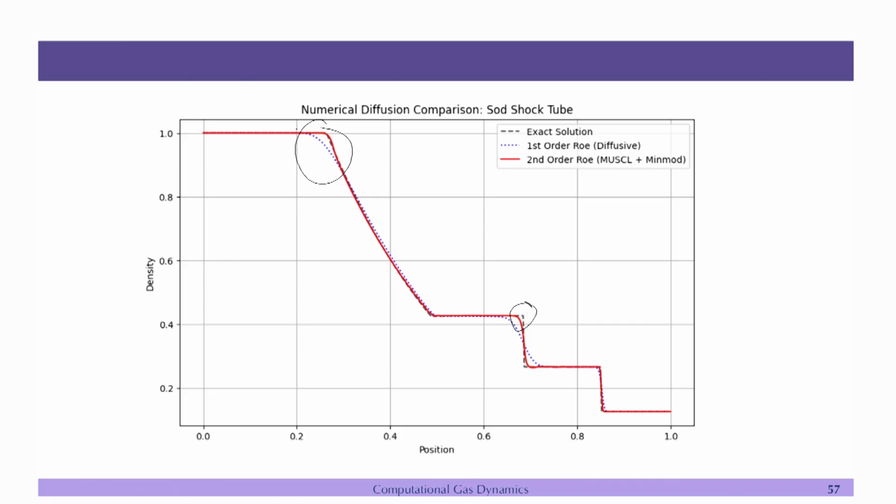And when we are talking about computational gas dynamics and flow which has shocks and expansions, it's a slightly different business, because you have strong discontinuities at different locations that you need to deal with. If the solutions are smooth, for example, incompressible flows or flows which do not have such big jumps, then you may not require these kinds of shock capturing schemes or special treatment near the discontinuities, right.